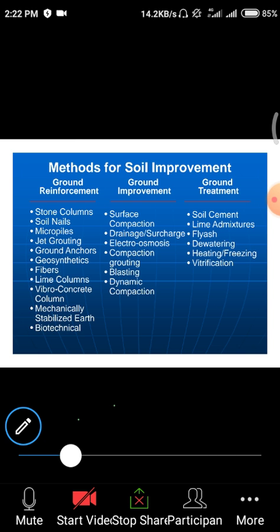That means by using these vibro flotation techniques and vibration methods, we need to densify the particular strata of material like these concretes and other stone columns and others like that, so that the strength properties will gradually increase due to these vibration methods and others.